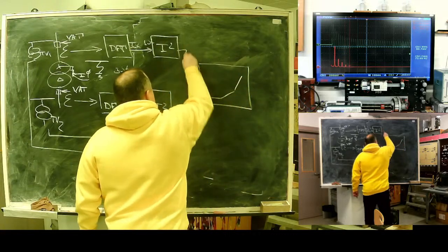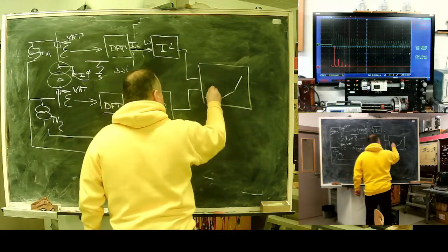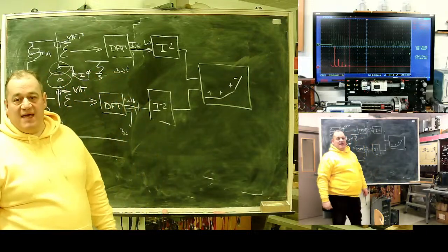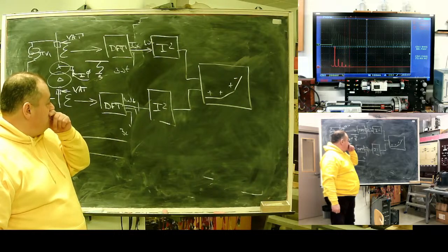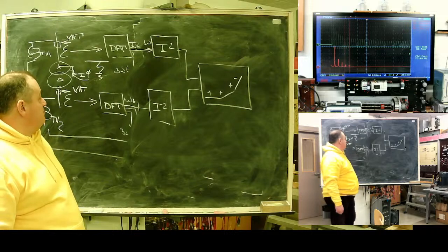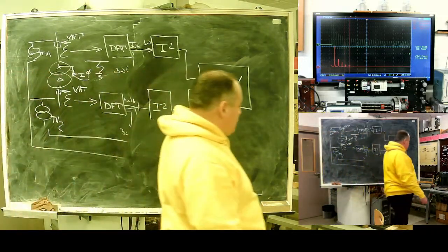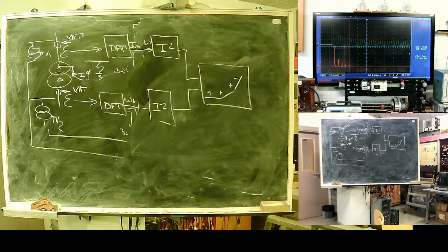It has the same design, but a much more sensitive differential characteristic for negative sequence. This will allow you to get high protection with high sensitivity. Negative sequence differential protection increases sensitivity for interwinding faults. One moment. Second,